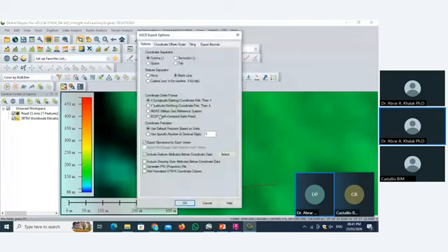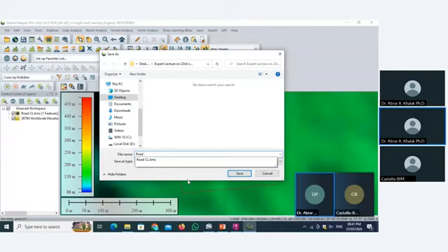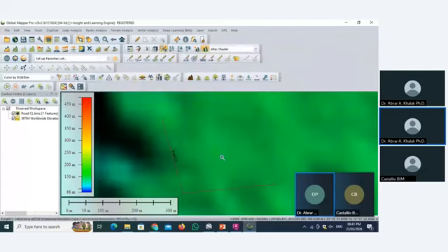Okay. Now coordinate separator, you have to select comma. Feature separator as blank line. Coordinate order format as X longitude. The rest of the things are okay. Now file name. So this is our road center line, we type road center line, and this is in text format. Okay, save. Done. So we exported our road center line points in TXT format.